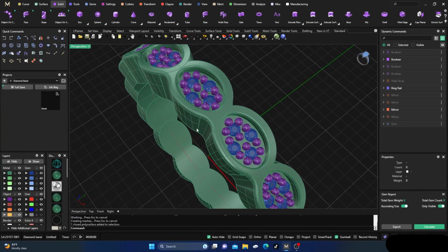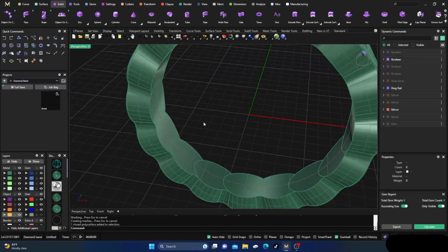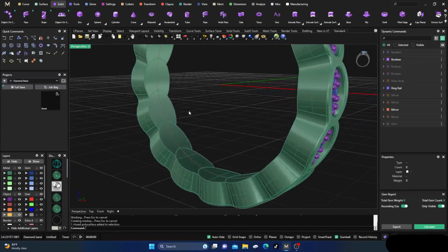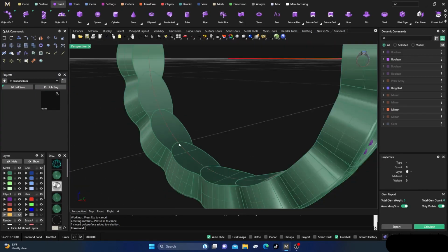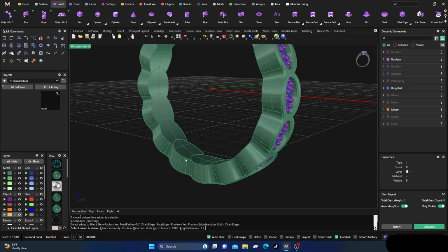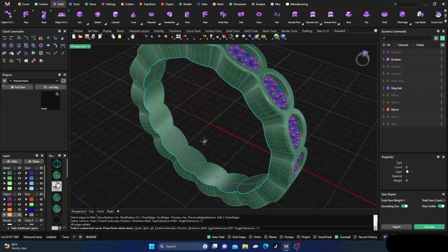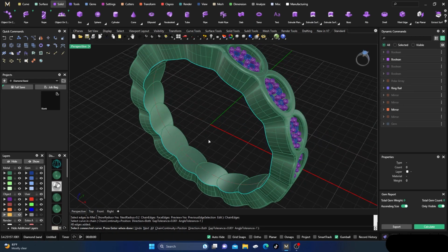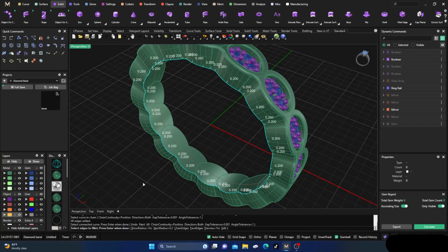So now we have this side pretty much all smooth. Oh, that in there we should probably do to the bottom of our shank. So I'll right click, bring that back. We'll go to chain edges again. We'll select this edge right here, and we're lucky it clicks it all. And we'll just keep that at a 0.22. Actually, let's bump, well, we're at a preview, yes. So we'll take a look at the preview here. We'll go ahead and hit enter.